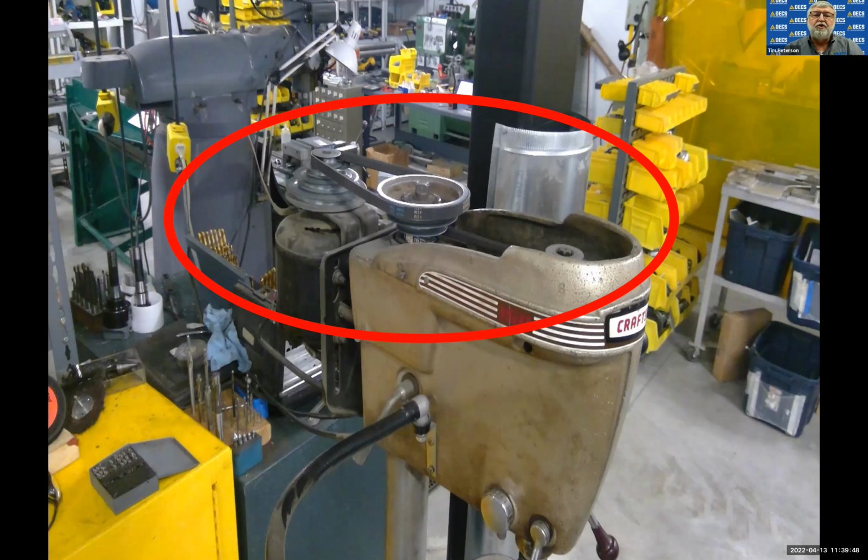So when you look at machine guarding, always ask yourself, did I create a barrier to prevent the employee from getting through, over, around, or under to the point of operation? And obviously in this case, that's not the case, because he or she could not only put their hand into it, but if they lean just correctly, they might get their hair caught in it or a piece of clothing. And that belt and pulley system isn't going to stop just because my finger got in there. It's going to keep on going and do some serious damage.